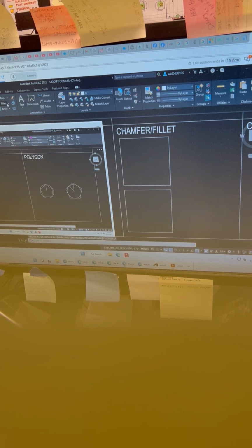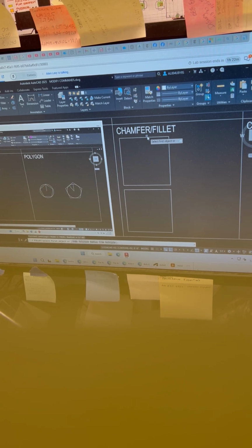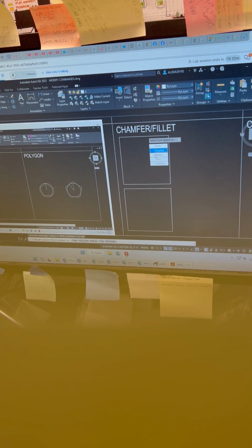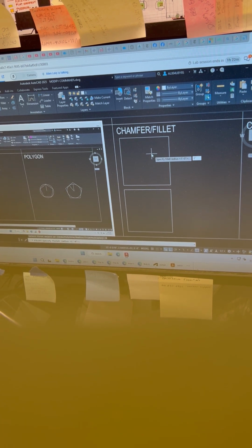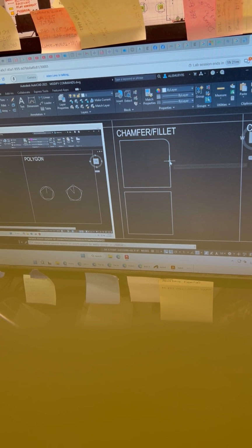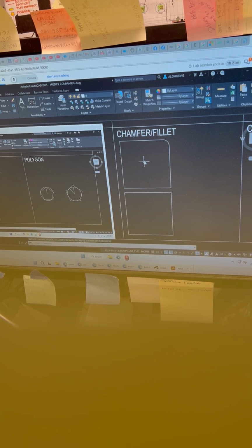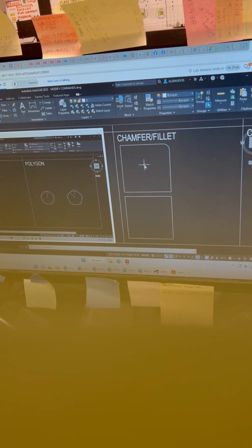All right. Why don't we try this? Let's change the radius to 6 inches. And I want to show you a way in which you can do a multiple fillet, meaning you don't have to stop after each fillet. See how the command just ended? It kicked us out of the command. We were done. But what if you have a lot more fillets? What if I want to add a 6-inch round fillet to each one of these corners here?